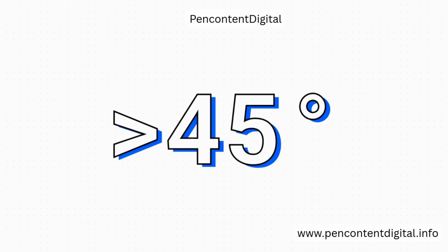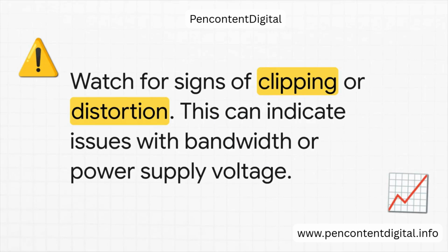But hey, gain isn't the whole story. We also need to check for stability to make sure the amplifier isn't going to just oscillate like crazy. And for this, we look at something called the phase margin. Think of it kind of like a safety buffer. A value over 45 degrees is a really good sign that our circuit is stable and it's not going to misbehave on us.